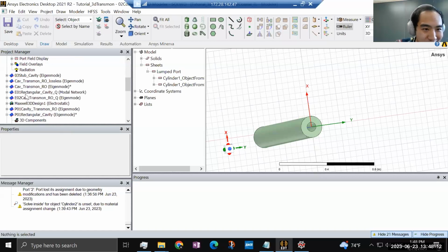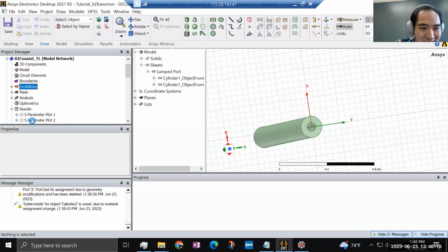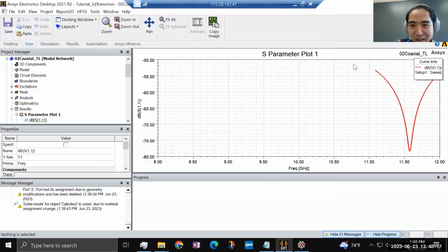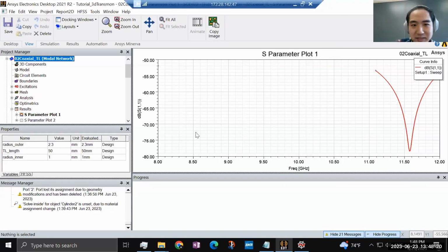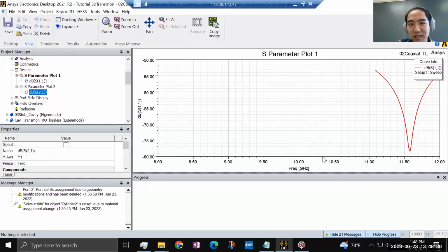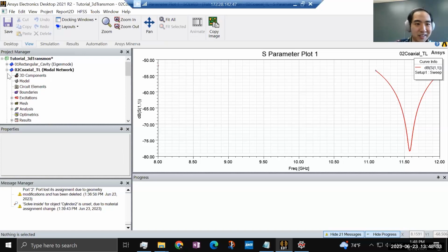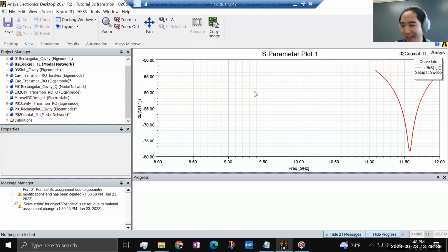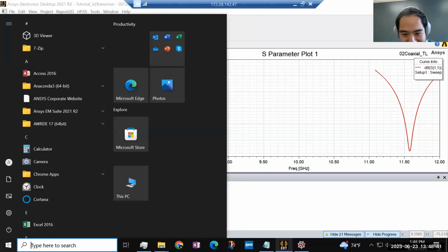And I'm sorry for not keeping track of the time, but this is essentially what I want to show you: that in a driven model simulation, it should give a scattering parameter versus the frequency scan between the 2 ports. So S11 stands for reflection and S21 stands for transmission. But yeah, I agree, these are all details of the software. So I apologize for this part taking way too much time. But I think it's more important and more valuable to go to the